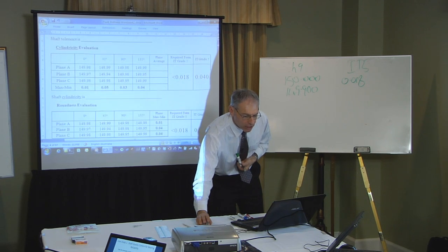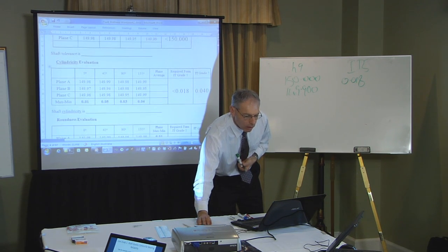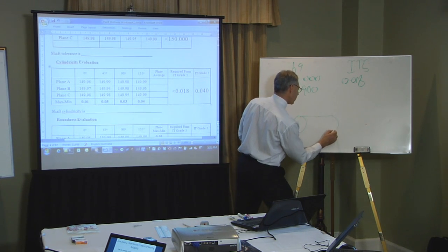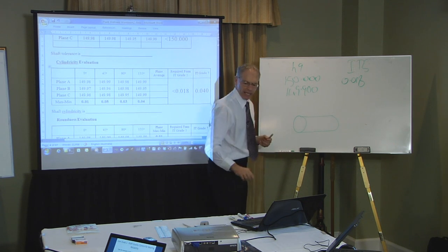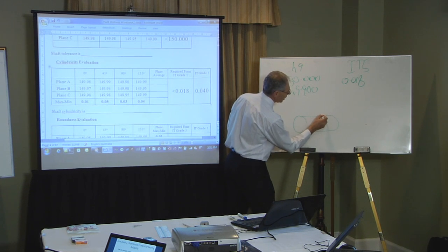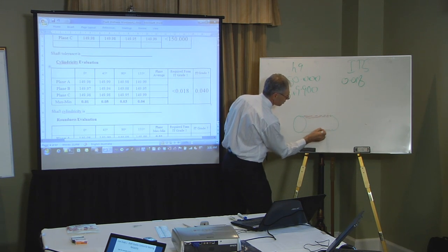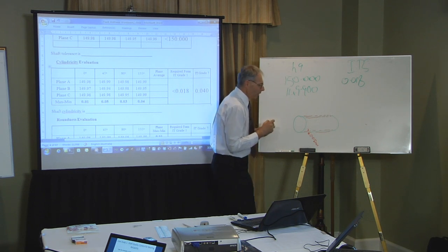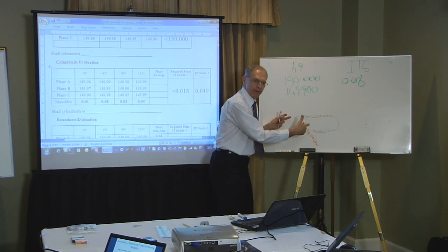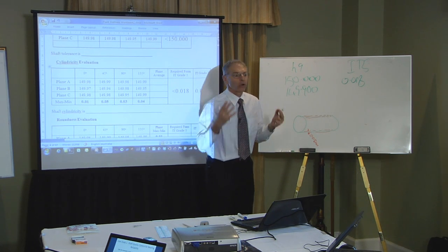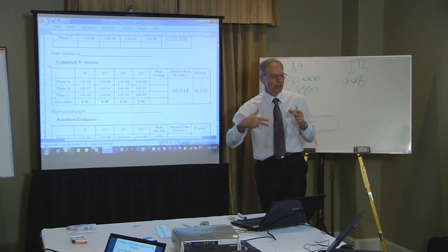It says to check the cylindricity. Now cylindricity, if I sketch that out roughly, what it's saying is, is it cylindrical enough to be acceptable? And we have an 18 micron tolerance, 0.018 millimetres. That shaft section where the bearing sits must be cylindrical enough to be within those boundaries. Outside of those boundaries, it isn't cylindrical enough to take the bearing and sit it properly.